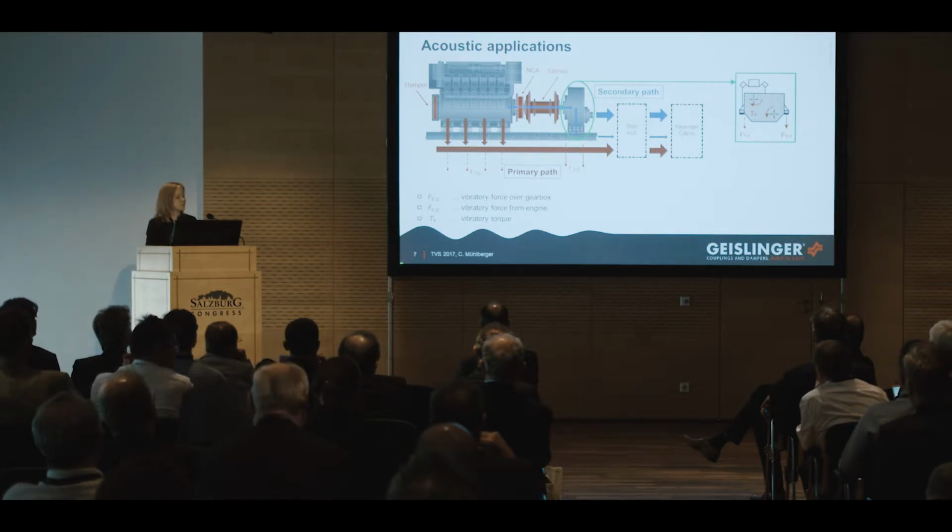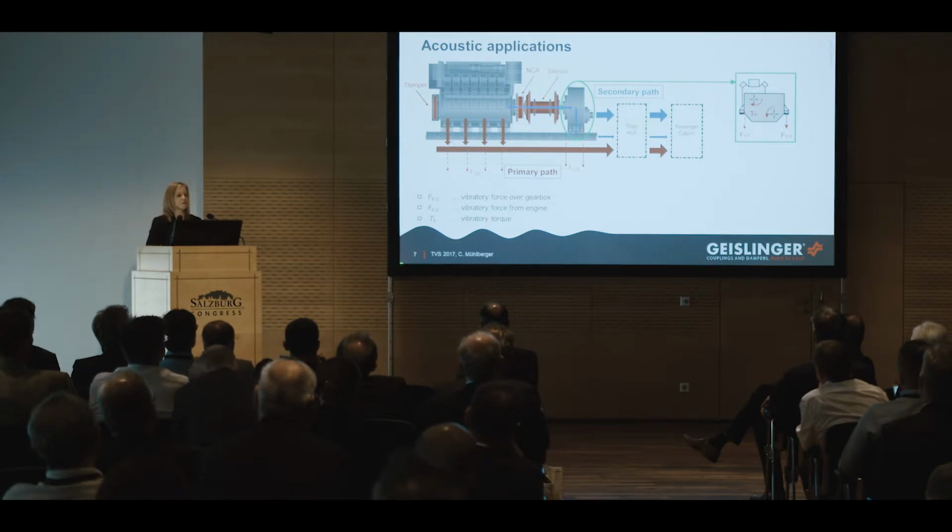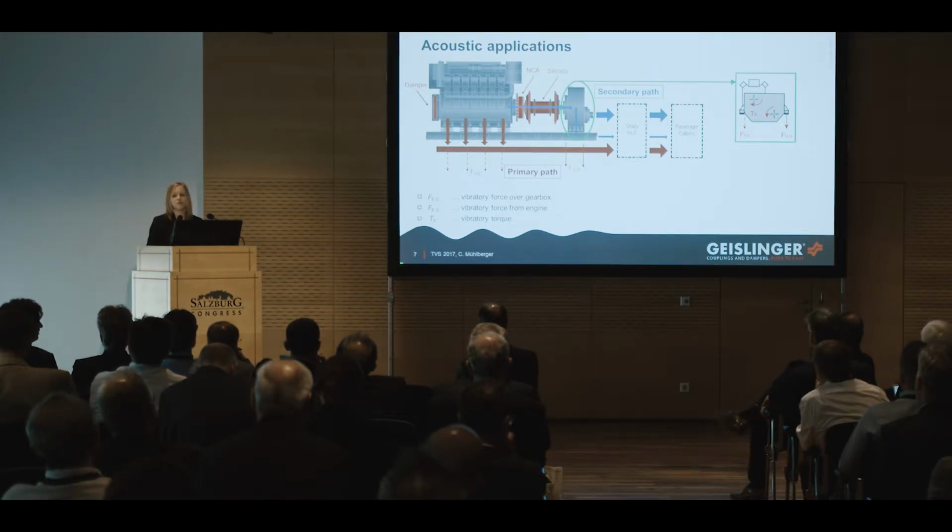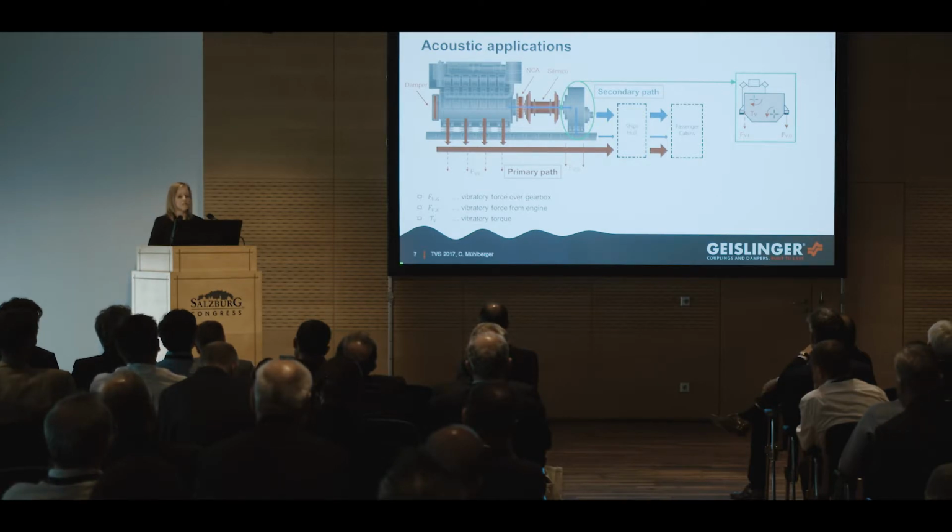So one would like to apply a soft coupling. But as we know, in acoustics and sound-sensitive installations, we often have the restriction that the permissible vibratory torque has to be about 3% of nominal torque or even lower. And as we know, very low vibratory torques and very low vibratory twist angles have a high stiffening effect, a high dynamic stiffness for the coupling, and a stiff coupling is what we wanted to prevent in the first place.